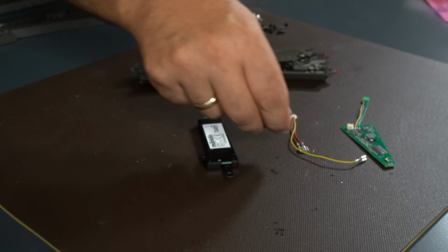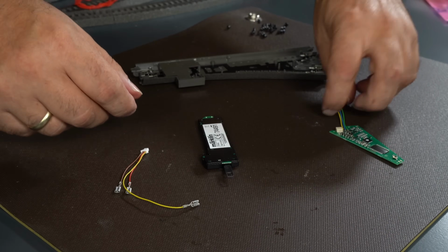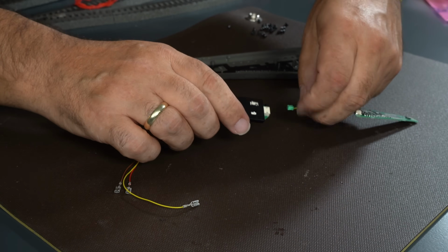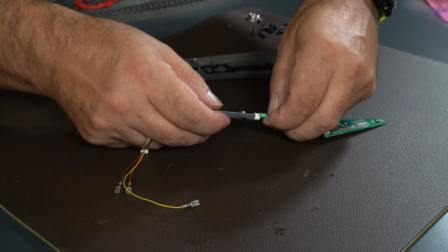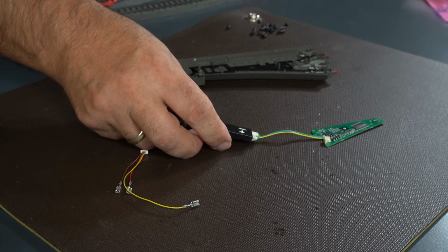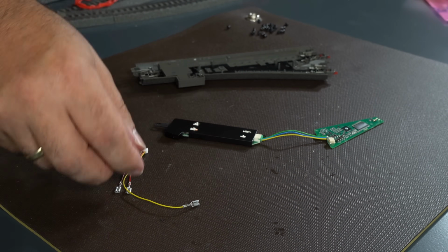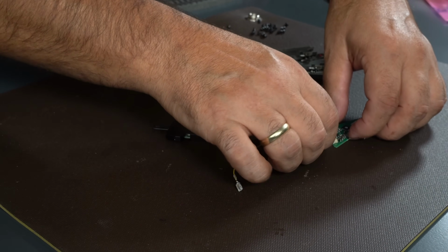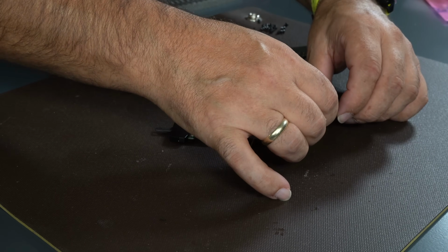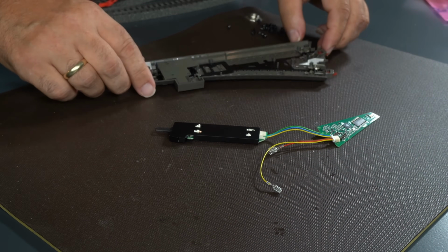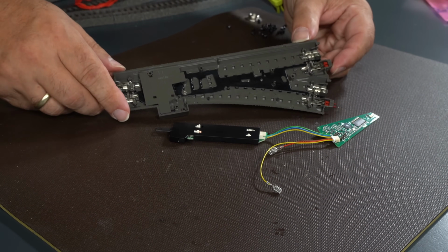Now we take the decoder and the drive, and on the decoder we have the plug, which must be plugged into the drive the right way around. You should always do this before installing the whole assembly into the turnout, because it will be too difficult to do later. Yes, and then we take the power supply unit, which is specifically designed for the decoder, and it is also plugged into the correct interface accordingly, making sure that all connections are secure and properly aligned.